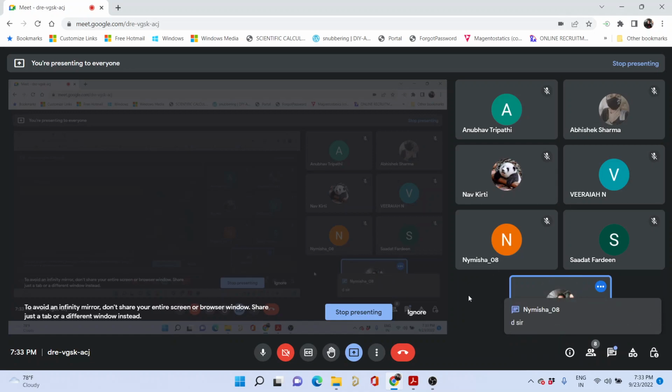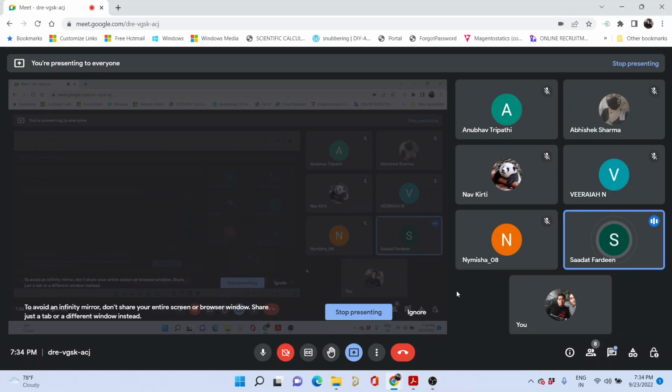Okay. Can you tell why do you think it is D? We have to find the H of omega, and that is only the imaginary axis. Why is it on the imaginary axis? Because it's the S plane, and the j omega axis is the set of all omegas. And why would we put S equal to j omega? Because they have asked for H of omega. Is there any other reason why they have asked for H of omega?